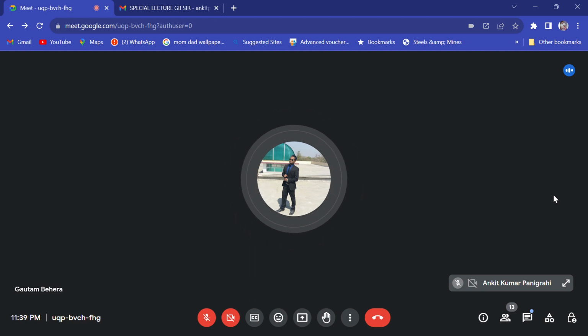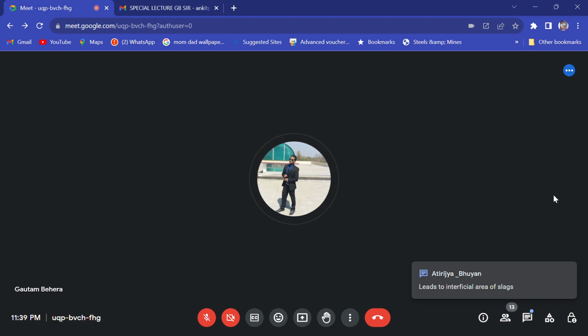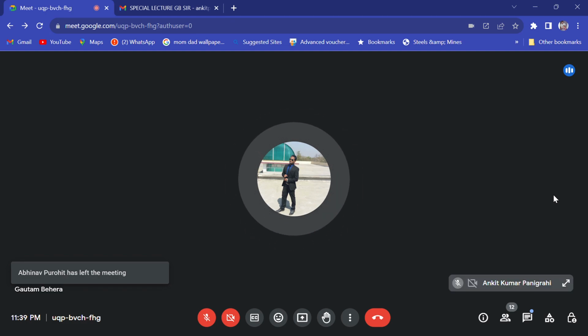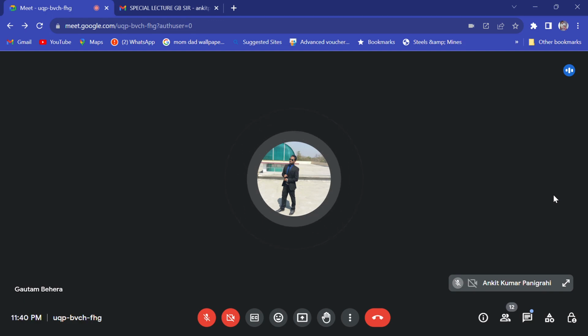Emulsion means these are droplets actually. Droplets of what? Droplets of gas, metal, and slag, right? Due to formation of these tiny droplets of gas, slag, and metal, the surface area will increase to a large extent, right? Due to large surface area, the reaction rate will be high. So in this way, the impurity removal will be fast. That's why in the LD converter, impurity is removed within 20 minutes. That is the very advantage of the LD process, because of this emulsion formation, right?